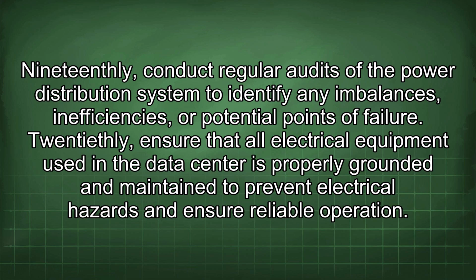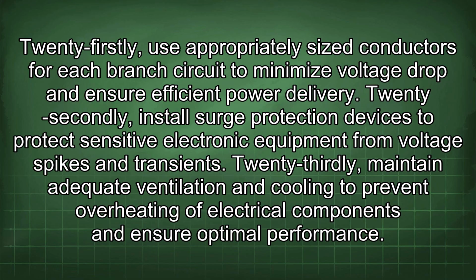20thly, ensure that all electrical equipment used in the data center is properly grounded and maintained to prevent electrical hazards and ensure reliable operation. 21stly, use appropriately sized conductors for each branch circuit to minimize voltage drop and ensure efficient power delivery. 22ndly, install surge protection devices to protect sensitive electronic equipment from voltage spikes and transients.